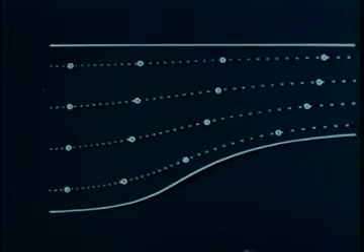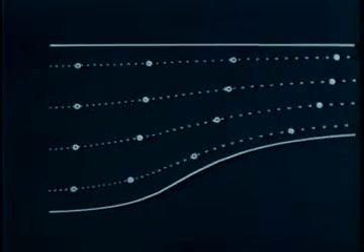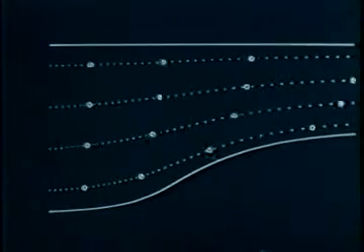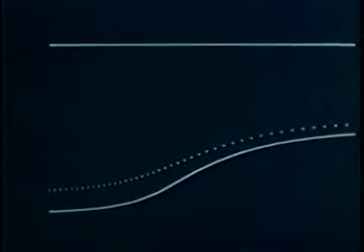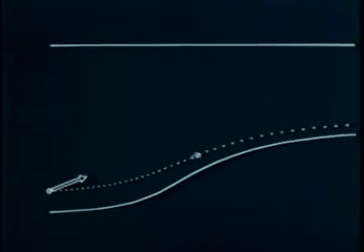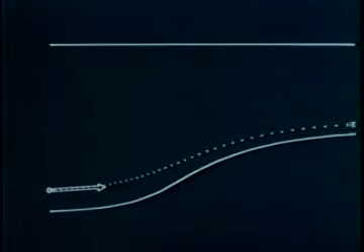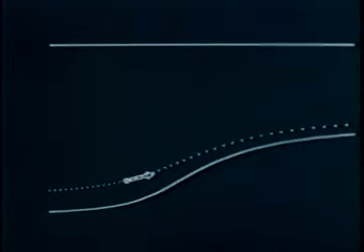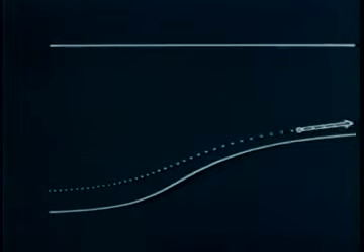In a continuous fluid, of course, we have an infinity of mass points, and we have to find some way of tagging them for identification. A convenient way, though not the only one, is to pick some arbitrary reference time, which we will call the initial time, and identify the material point by its location at that time. Mathematically, we would say that the velocity is a function of initial position and time. To accord with this description, we have shown the vector attached to the initial position. We could show the vector attached to the moving point, or use both.